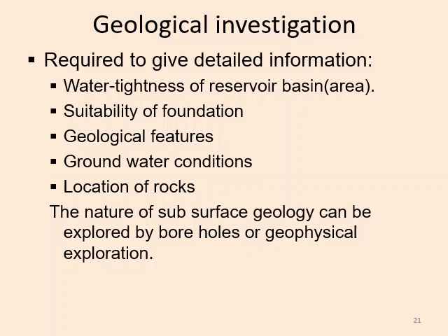Next are geological features over the ground and also under the ground. Groundwater condition means where the groundwater table lies under the exposed surface. Location of rocks under the earth surface means where we will get a rock mass which we can consider as a suitable foundation layer. The nature of subsurface geology can be explored by boreholes or by geophysical exploration.